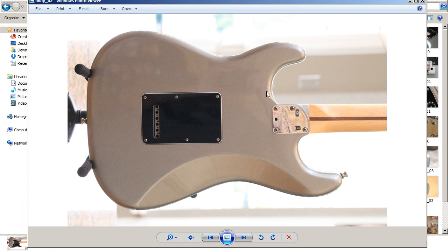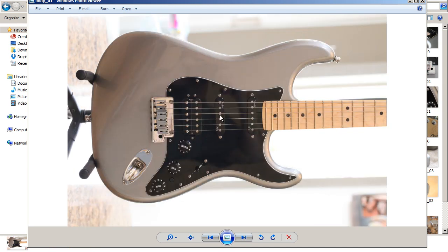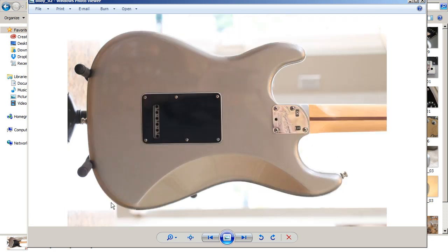So if we were to go in and create that ribbon shape at the correct thickness, we can fill in the top, and we can fill in the bottom as well. Once we do that, we can cut this out in one big swoop. We can just take a big cube and boolean it right out of there. That way we can keep this nice and flat right here. We don't want to get a lot of geometry built up in here and have a problem getting this nice and flat. Same thing here. Once we get that ribbon around there, we've got one big face here that we can cut this out.